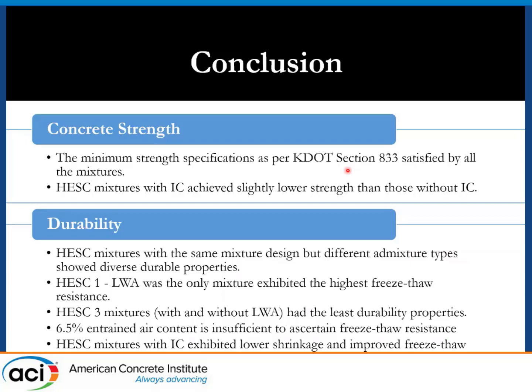The HESC1 admixture combination with internal curing was the one with the highest freeze-thaw resistance, while HESC admixture combination number 3 showed the least durability properties. And as I said before, even though they had the proper fresh total air content, it was insufficient to ascertain the freeze-thaw resistance. We commonly believe that if we hit the minimum total air content, we will have proper freeze-thaw resistance, but that's not the case.